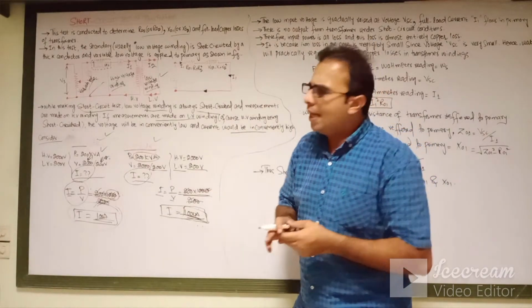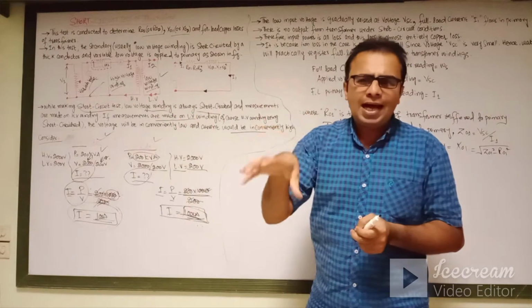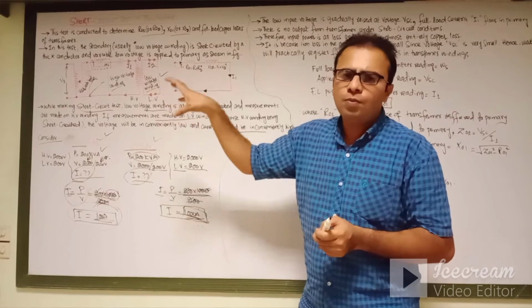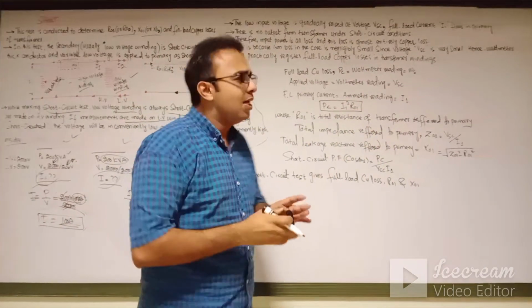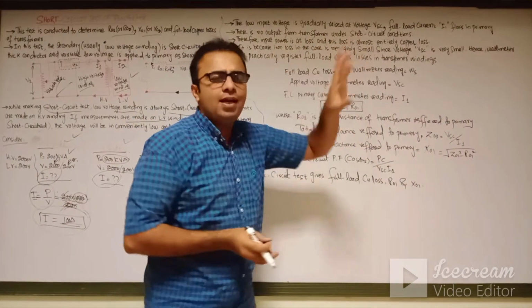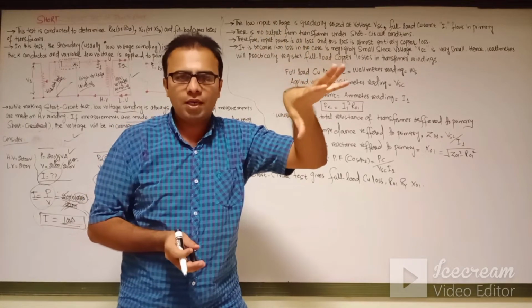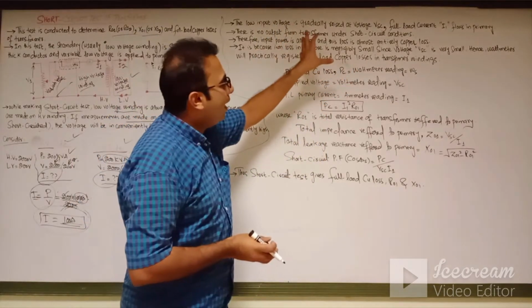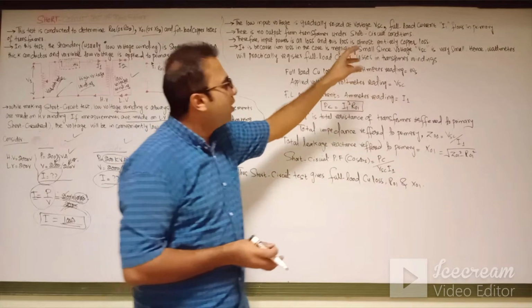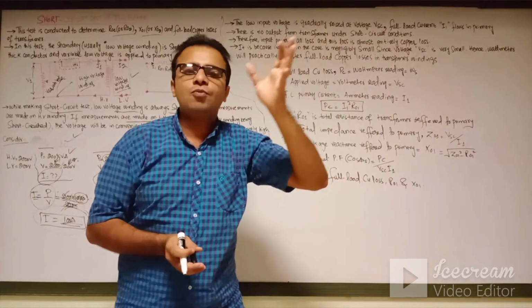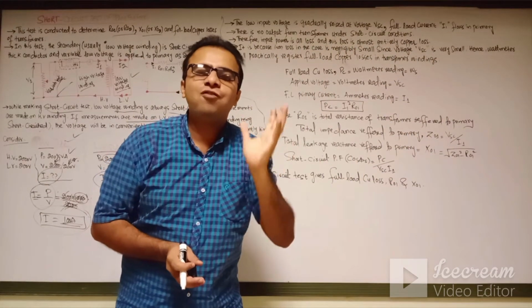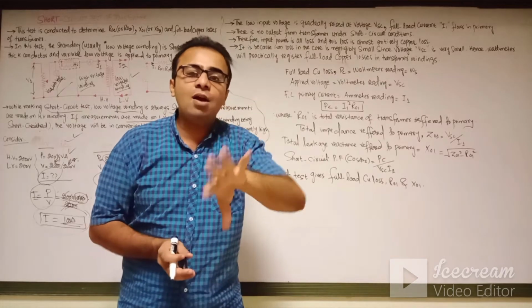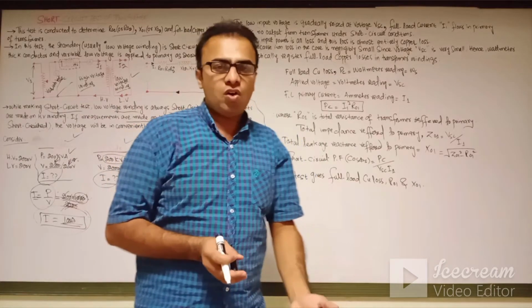What happens is that the voltage is raised until it reaches VSC, the short circuit voltage, at which the full load current I1 flows from the transformer, and that current represents the copper losses in the transformer.